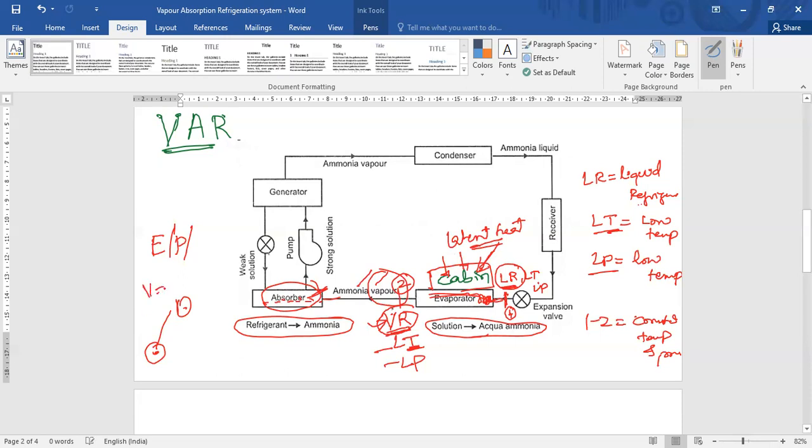because the volume of the gas is more. So you need to compress it first, or else we need to mix it with another solution. And one more point you need to remember here is, as the temperature of the gases increases, the viscosity decreases. So we need more energy to pump the ammonia vapor from the evaporator to the condenser. That is the reason they mix this evaporator refrigerant with ammonia solution. Whatever refrigerant is coming from the evaporator is in vapor state.